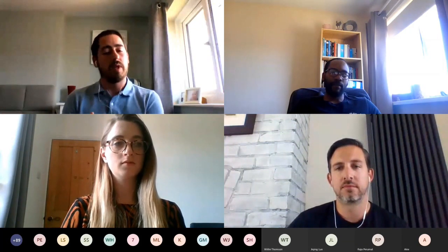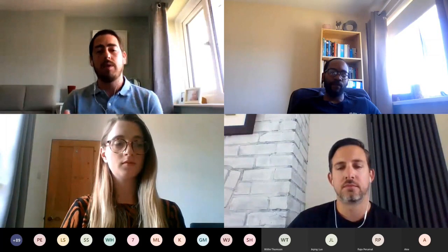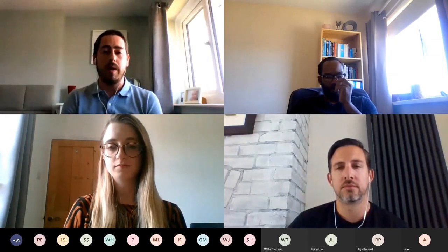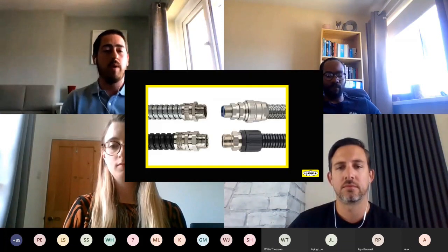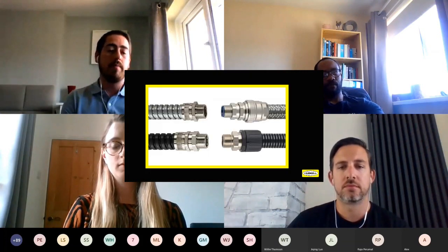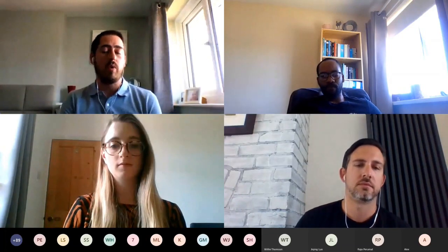With flexible, you would need an additional gland, and these cable glands are designed to have a female entry on the back that allows you to attach that additional cable gland for IP around the flexible conduit, and maintain obviously the integrity of your equipment or an enclosure.